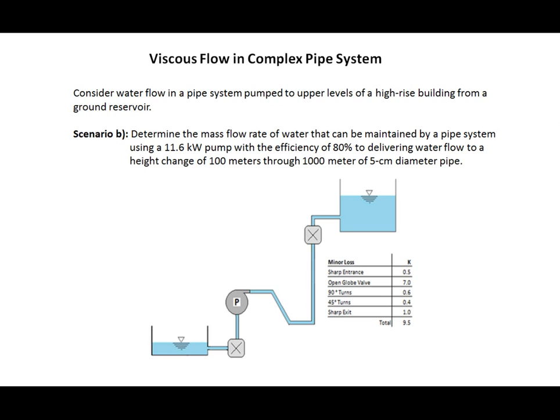Now let's look at a variation on this type of problem. In other situations, you may know the pump power, but you may want to solve for the height change, mass flow rate, pipe diameter, friction, or other losses. As we know, some of these require iterative procedures that can be time-consuming. With ThermoFlo, we can do these calculations easily by making a simple change and rerunning the problem.